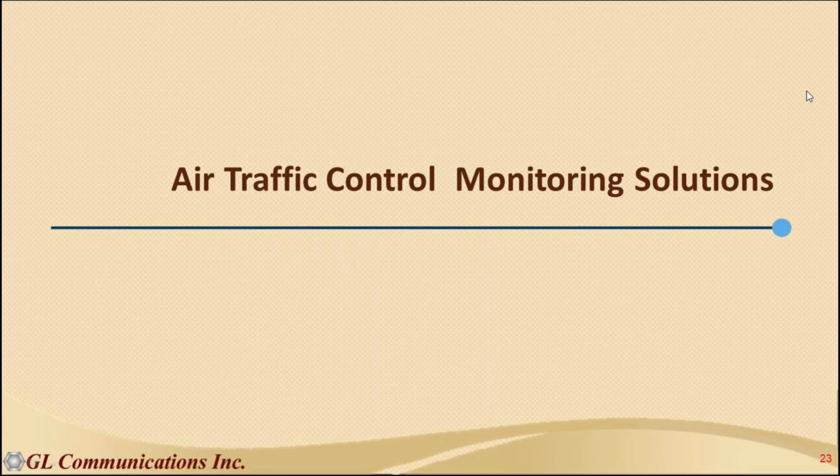Hello, good morning. I'm Marius Irlbeck from Eurocontrol in Maastricht. My question is about how you manage to detect the simultaneous calls when it involves an ATCO and the pilot. I understand the squelch and the PTT are both active at the same time, but this happens also when it's only the controller transmitting. I would like to know how you differentiate between a squelch coming from the controller and the squelch coming from an aircraft call.